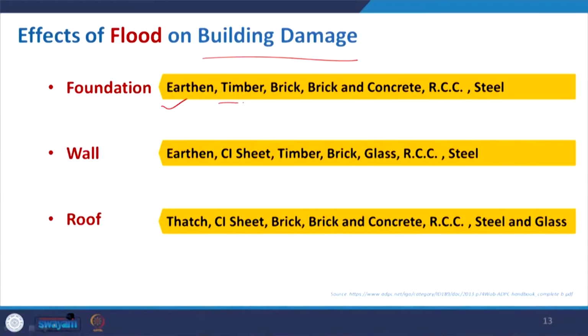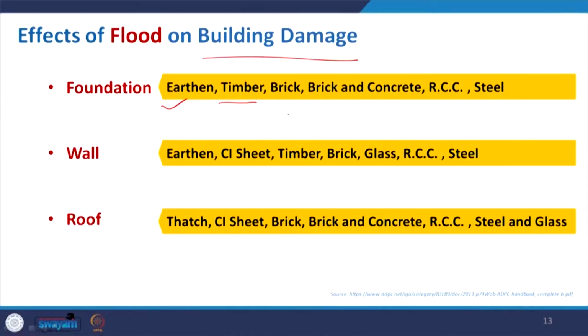Even sometimes if you make it with timber or light material and it is not anchored properly, the whole building can be blown away with the flow, and there are many instances of that. A brick, or brick and concrete kind of foundation may sustain a bit, and if it is RCC or steel, that will sustain depending on the depth, whether you go for an isolated foundation or a pile foundation. So it also depends on the foundation.